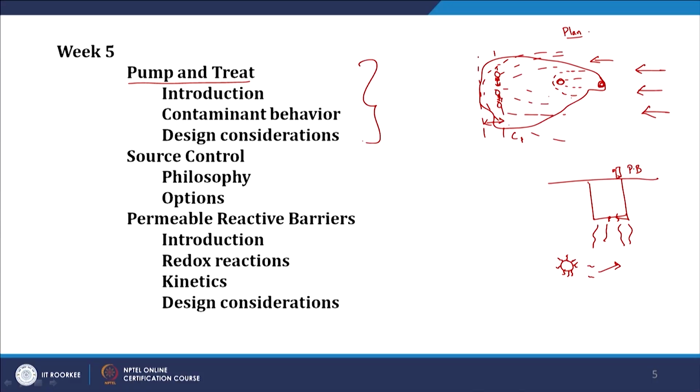So as you pump water out, and water with less concentration of this contaminant comes in contact with the soil, again you are going to have desorption. But again this takes time, and the soil acts as a reservoir of contaminants. So these aspects need to be considered in pump and treat.